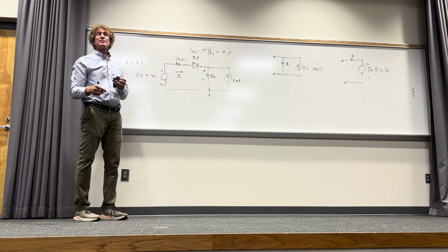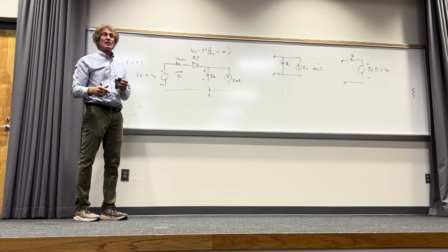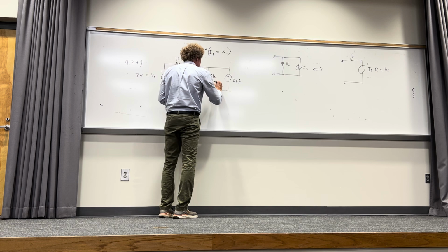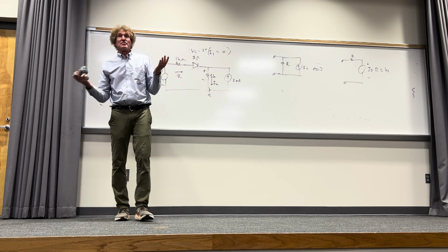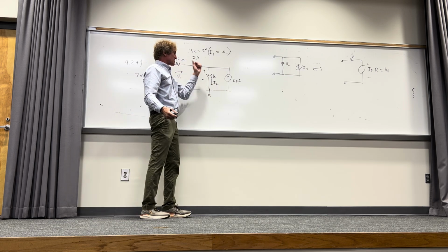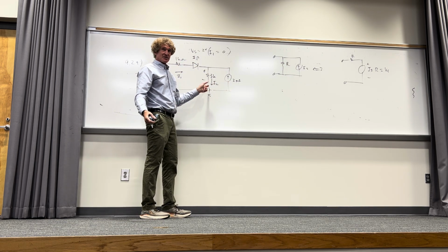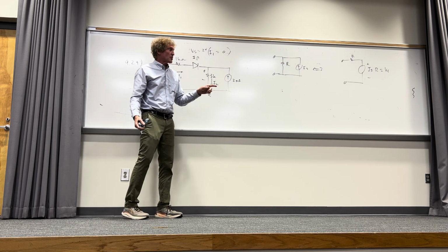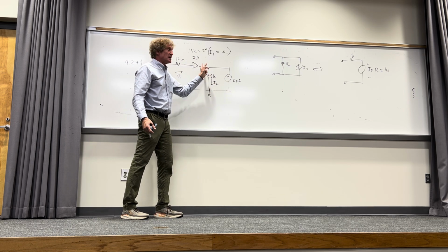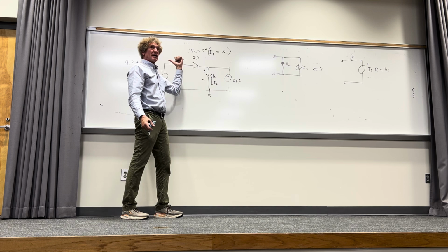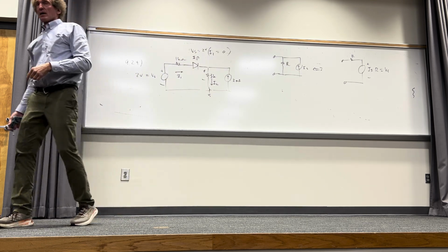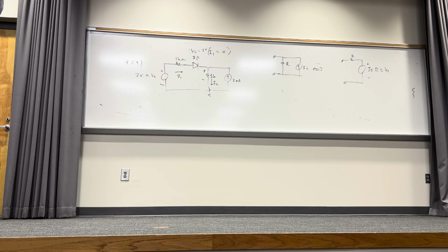Yes, sir. There was also an I2 closed with 3 kilo ohm resistor. Yeah, and what would that be, by the way, for the first part? It has to be, right? No current flows this way, but there's 2 milliamps. That has to flow down there. You all follow me? Just Kirchhoff's current law right there. Whatever goes in comes out. What's going in is 2 milliamps. Nothing can come out that way. Everything goes that way. Follow me? How many see this? All right.